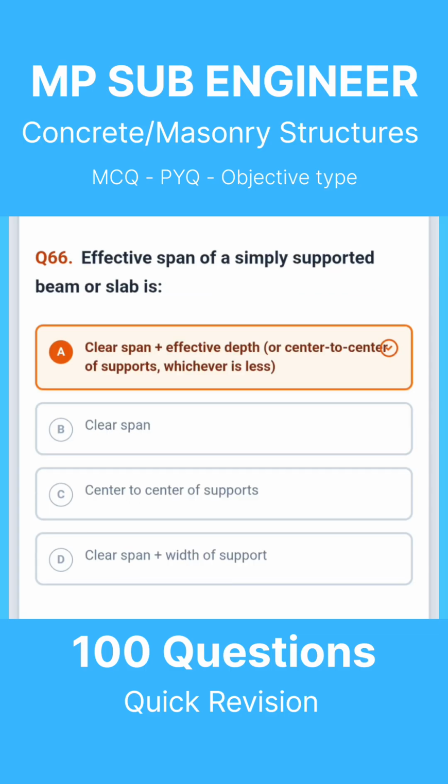Question 66. Effective span of a simply supported beam or slab is. The correct answer is clear span plus effective depth, or center to center of supports, whichever is less.